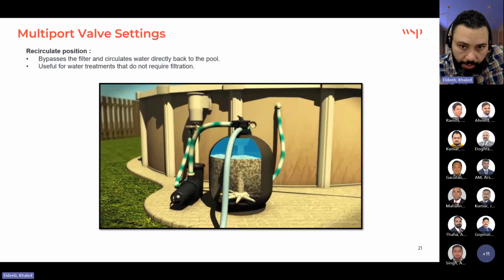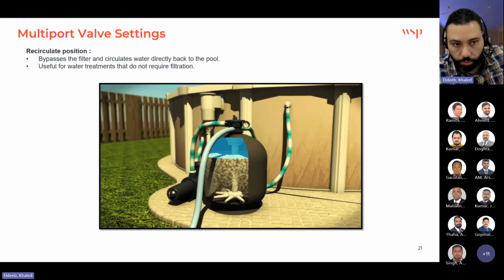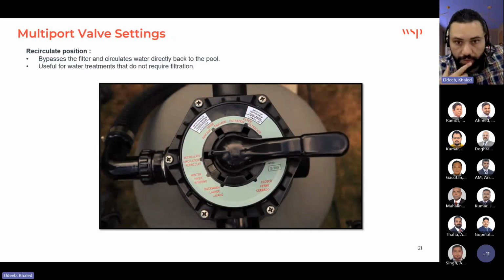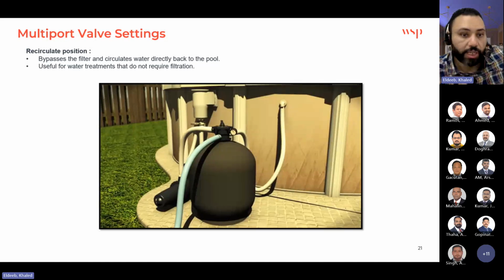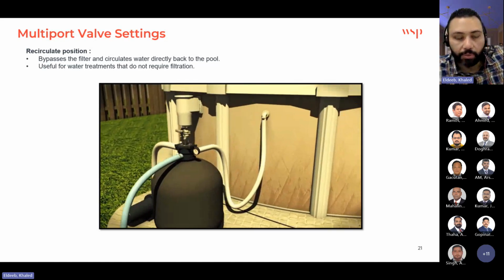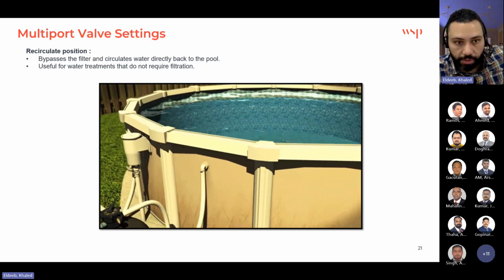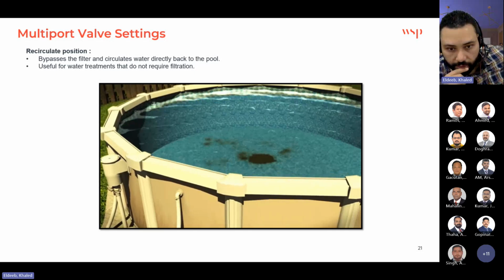First, we need to completely clean the pool to ensure there is no sand, and then switch it to the recirculate position and keep it in operation for a long time, overnight. Keep it working all the time. You make sure before leaving that the pool is clean, with no sand, and then come back the next day.